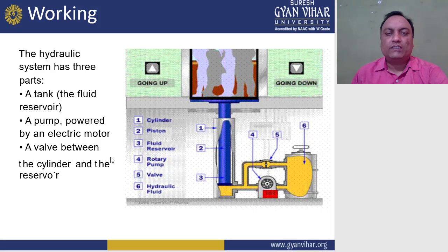So this works on the force generated in a cylinder system. The force generated depends on the size of the piston. If the smaller of the two pistons is 2 inches, and the larger is 6 inches, or 3 times larger, the amount of force created is 9 times greater than the amount of force from the smaller piston.